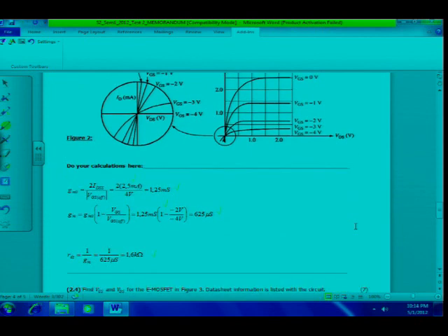Right, there's a solution. Formulas from the formula sheet. GM0, you would get then 1.25 millisiemens. Some of you wrote there a small s, which means seconds, of course, which is wrong. And remember that your answers should be expressed in engineering notation. So if you didn't do that, or you scratched out so that I couldn't read, you also didn't get the marks.